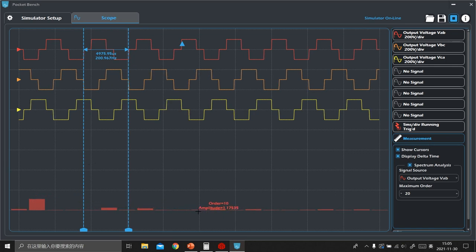So it's the same as what we got when we set the frequency to 100 Hz. So even if you change the output frequency, the amplitude of the output voltage can't be changed. So for the 3-phase square wave inverter, the amplitude of the output voltage can't be adjusted, and it contains a lot of low-frequency harmonics. We'll solve these issues in our future classes.